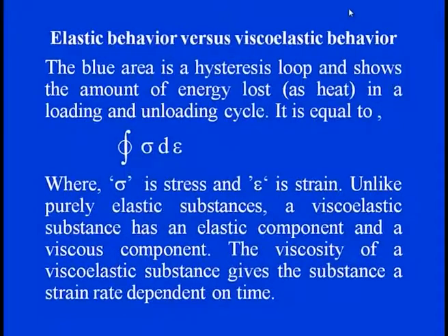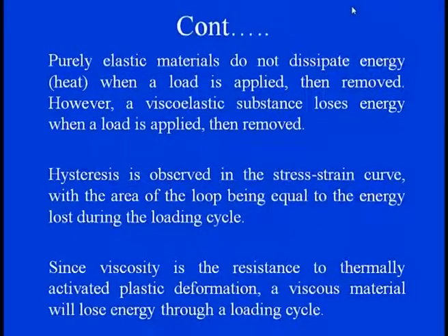Like you see, a viscoelastic substance has an elastic component and a viscous component, and this viscosity is basically responsible for this energy loss, and this always makes the substance's strain rate dependent on time. When we are talking about a pure elastic material, there is no energy dissipation when loading and unloading conditions are there.